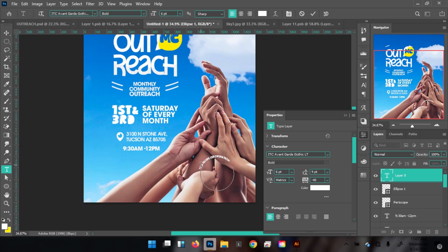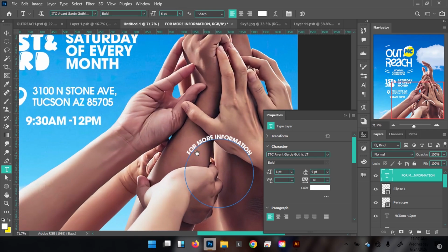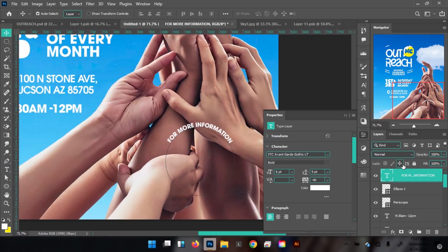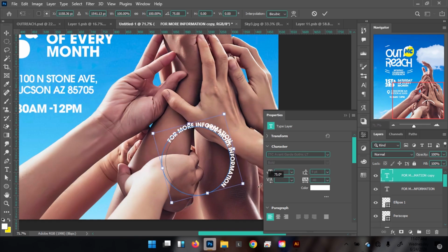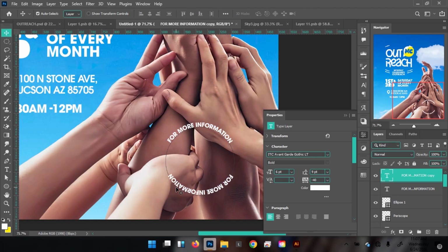So let's just click here, then move our insertion point somewhere like so. Enter, control space, zoom in, and create a duplicate of that same layer. So control J and control T, hold shift, and then move it downwards somewhere like so. So you are going to get something weird, so you have to reposition. So enter and then reposition. Use the arrow keys to reposition the duplicate in place so that it matches the one on top, and hide this as well, and then lock it.